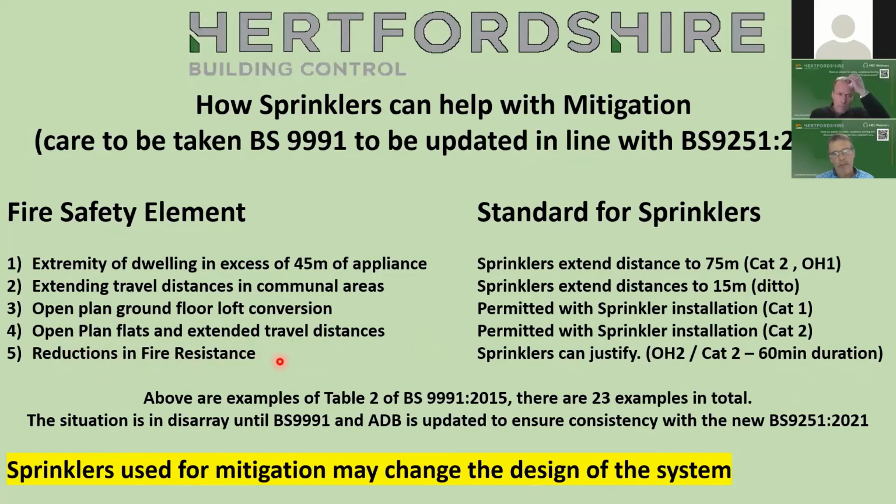So any reductions in fire resistance, the first thing I'm on the phone to, or I'm picking a consultation out, is to the fire authority. Because we should, as users of the building, be out in 2, 3, 4, 5 minutes. The fire resistance is 60 minutes and higher fire resistances. They're there to protect the fire service. So the last thing they want to be doing is fighting a fire in a building that may collapse. So if you ever think it's necessary to reduce the fire resistance for one reason or another, then the fire authority is key.